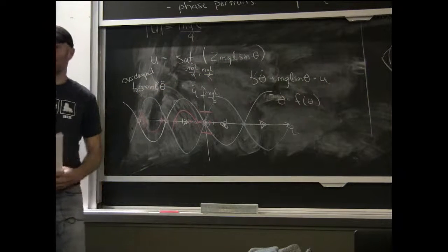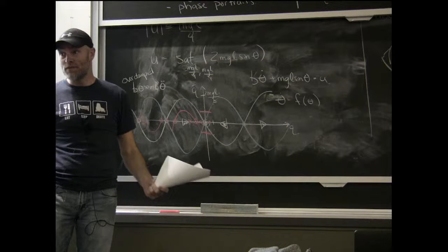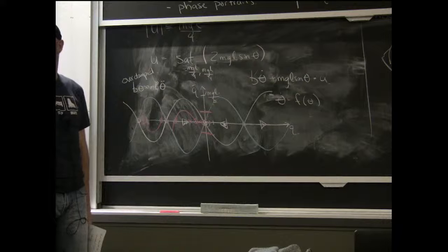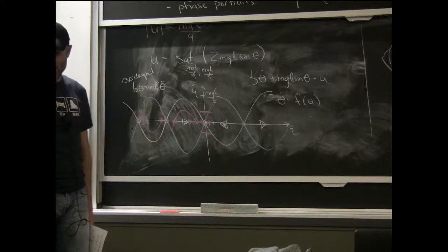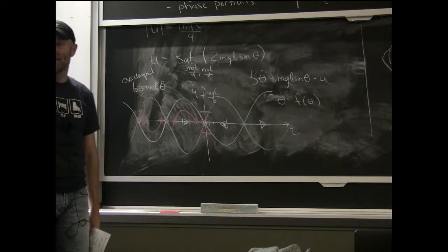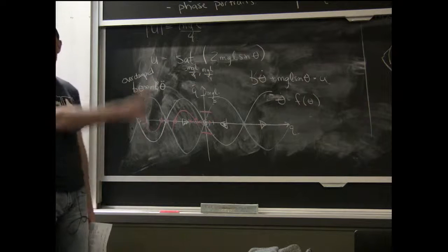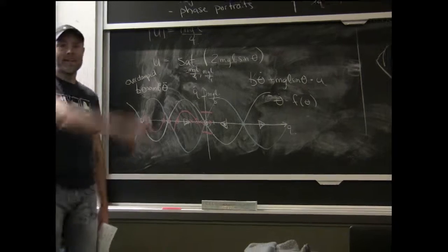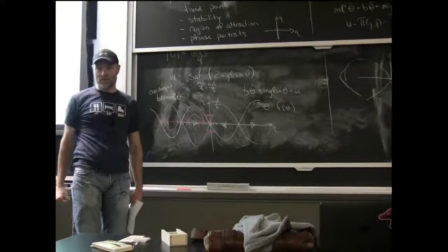But guess what? You can still get to the top, even if you have a little torque, right? So if you've ever been on a swing set, I guess you know that. If I put a little bit of torque in at the right time, and just keep adding energy, as long as I have enough torque to overcome the damping, that's my limit, then I can slowly swing up, and I can do great things with a little bit of torque.